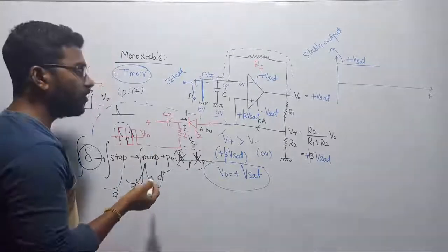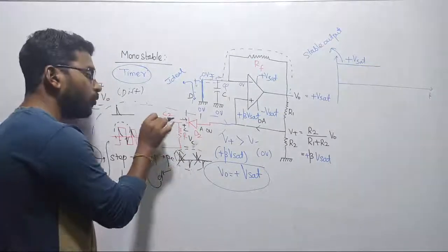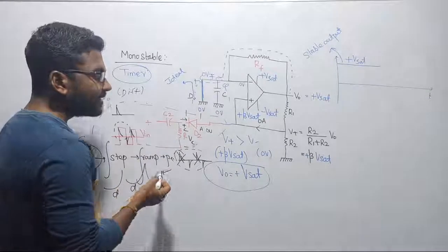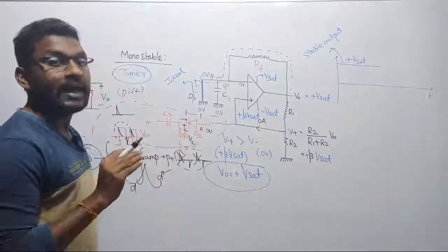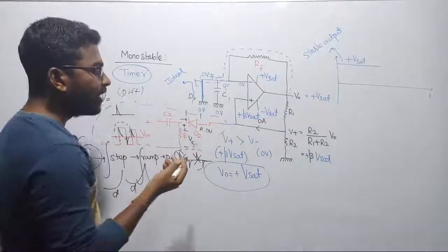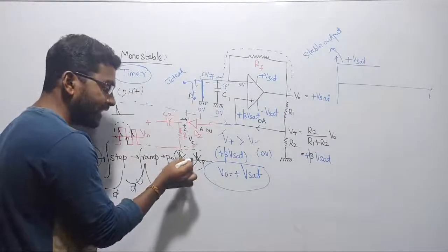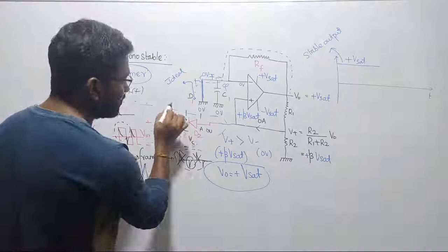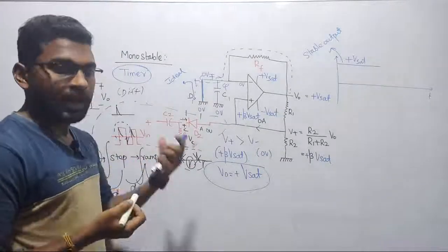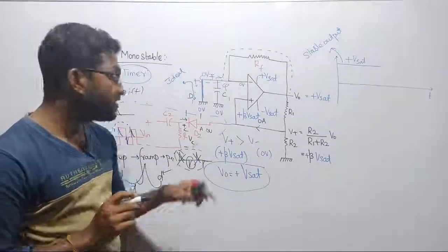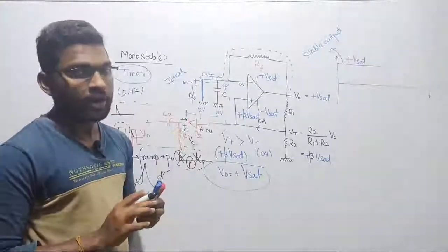Then which type of waveform will it produce? When we are injecting more negative voltage across the cathode, since the anode is not connected with any external mechanism or supply, the voltage across the anode will be 0 voltage. Voltage across the cathode, when we inject a negative spike, means negative voltage. So cathode negative voltage, anode 0 voltage, and 0 voltage is greater than negative. Do you guys agree with me?